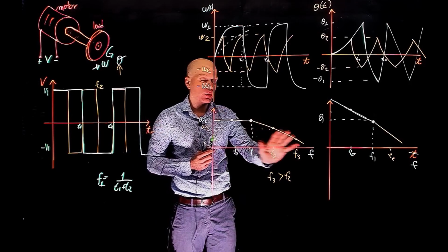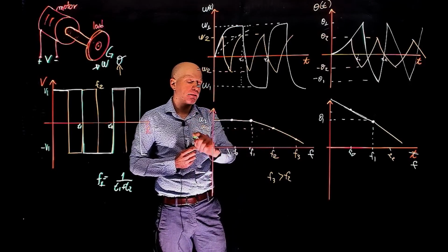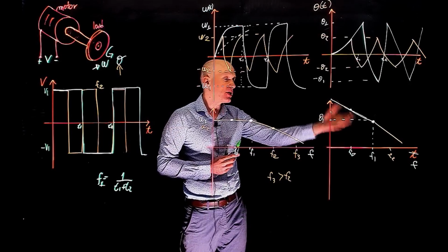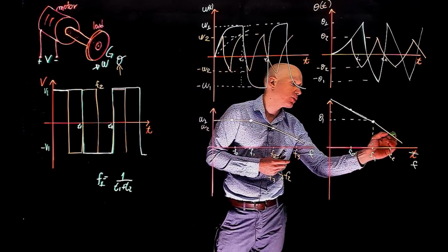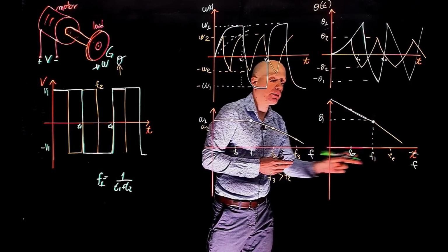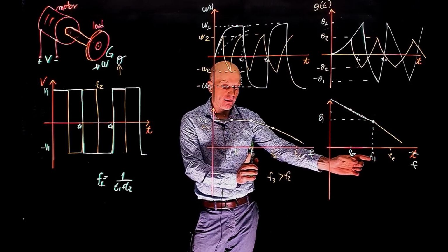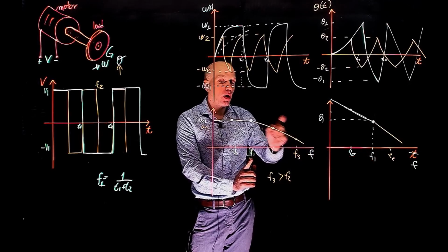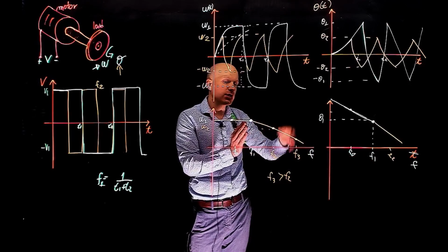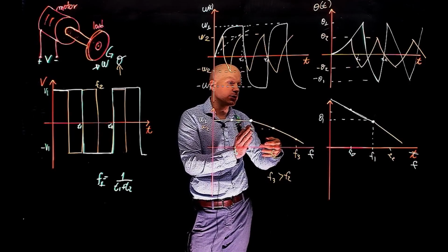If you now pass the frequency where we started to see the decay in speed, the position will decay faster than before. So this slope will also change. We had one slope here, and the slope will become steeper because now we are at that famous frequency f1, where we started to notice that past that point the system doesn't have enough time to develop its full speed.